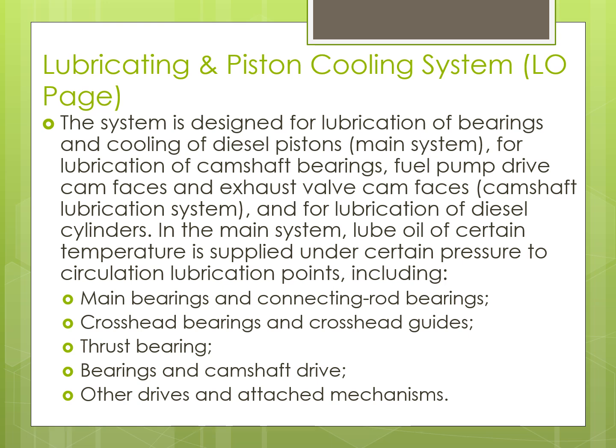In the main system, lube oil of certain temperature is supplied under certain pressure to circulation lubrication points, including main bearings and connecting rod bearings, crosshead bearings and crosshead guides, thrust bearing, bearings and camshaft drive, other drives and attached mechanisms.